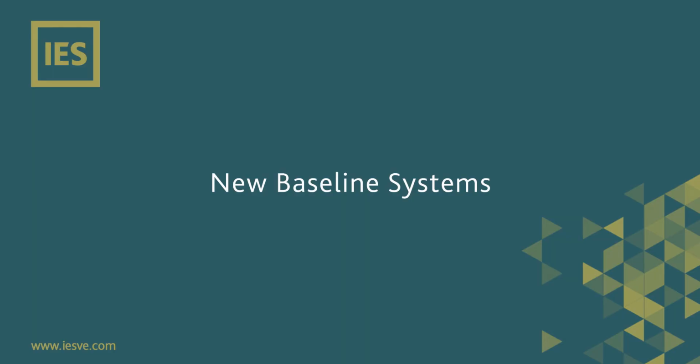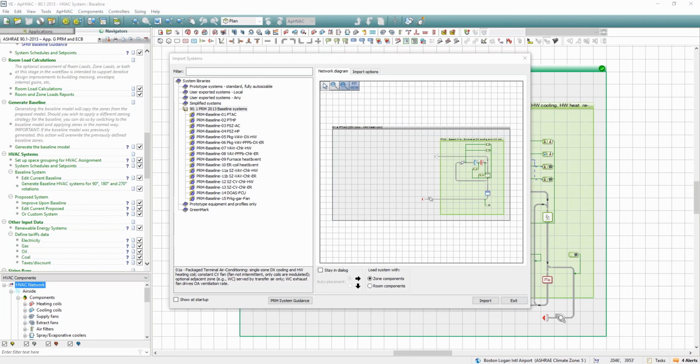New baseline systems. Two new baseline systems for public assembly building types have been added to 90.1 2013, namely System 12, Single Zone Constant Volume Hot Water, and System 13, Single Zone Constant Volume Electric Resistance. These are now available for selection via the 90.1 2013 Baseline Systems HVAC library.